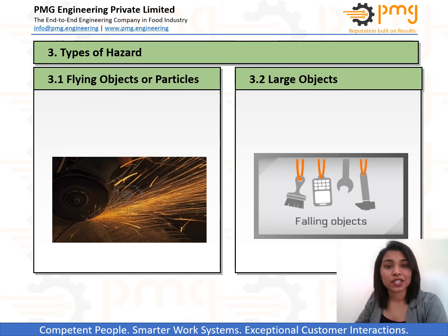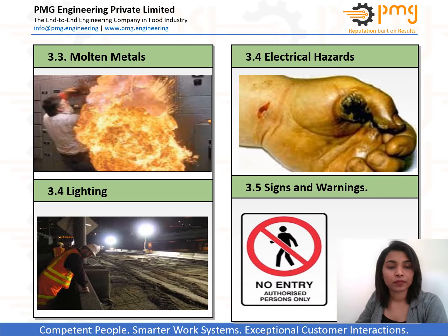Any sharp objects such as knives, scissors, pencils, etc. walking or falling into obstructions can damage your face or eyes. Swinging chains, cables, ropes, and tools that are thrown or fall can also cause injuries to face or eyes. Operations which involve or produce molten metals, if splashed, splattered or dripped into the eyes, can cause severe burns and tissue damage to face as well.